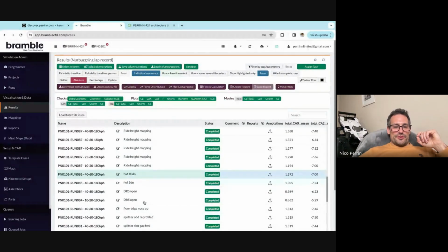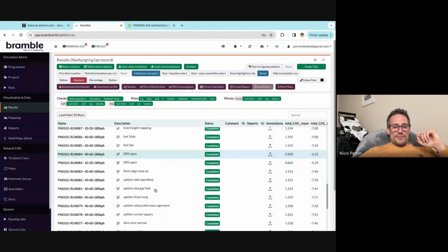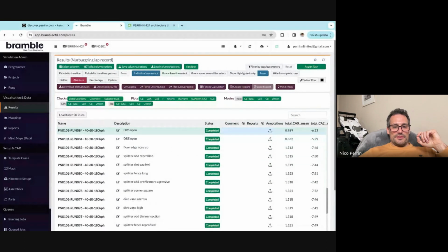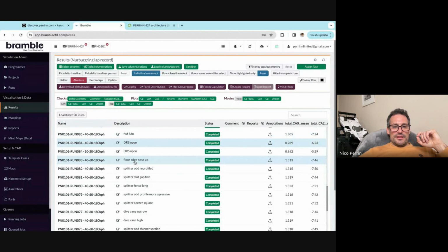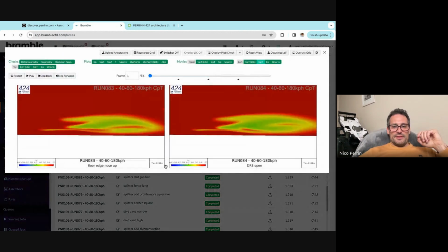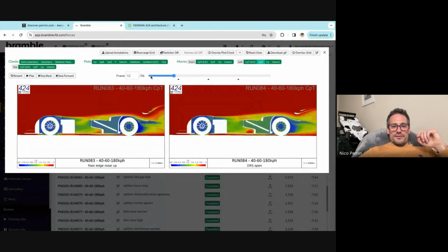So every test has got a simple name. In fact, we have a DRS open test here. We can have a quick look. A DRS open. If I select two tests, and then I can do the CP plots. Sorry, I'm going to take a lateral movie of CPT. Now I've got two movies, and I can scroll through, and you can see the DRS is open. You see the flow here, and the DRS is closed here. Just to show you how you can compare quickly what's going on.